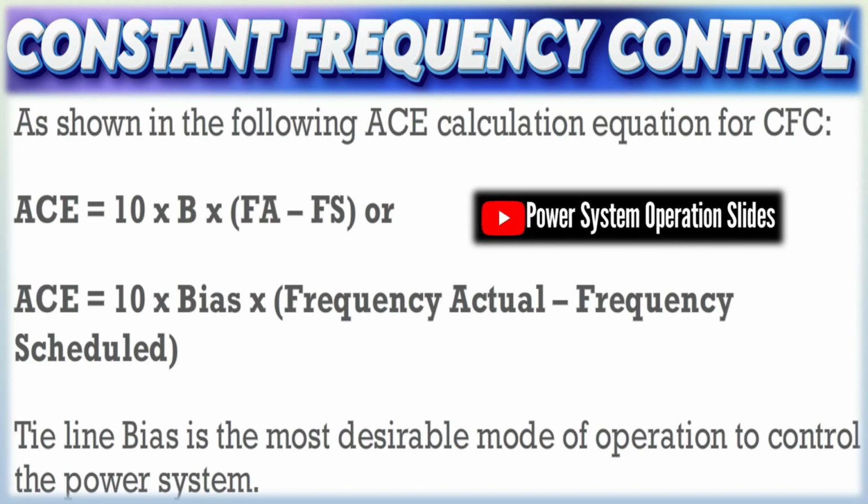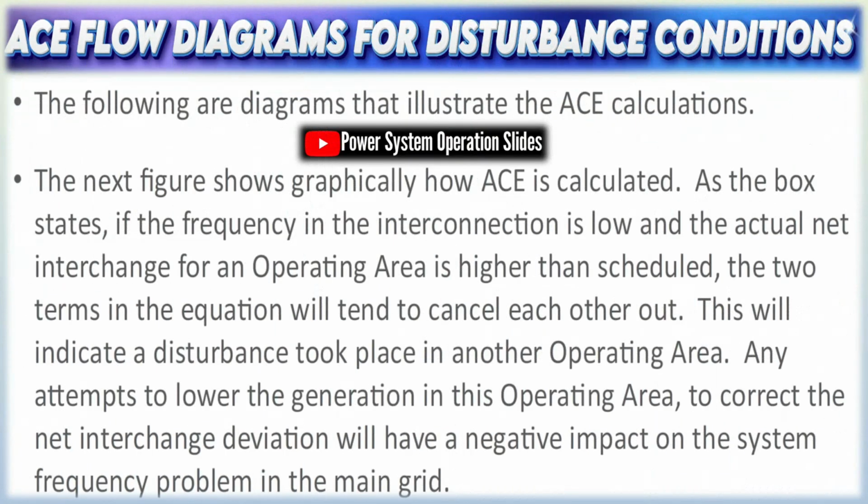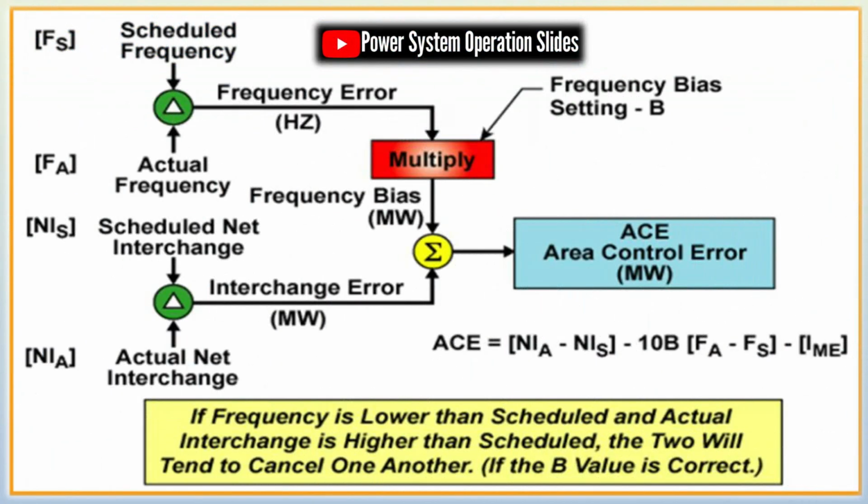It receives inputs from the Energy Management System (EMS) and uses them to send proper control signals to generation units. This interaction ensures that while the dispatcher may optimize the overall generation mix for economic efficiency through economic dispatch processes, the AGC fine-tunes the instantaneous generation to counteract fluctuations, thereby maintaining system stability and the contractual interchange levels.